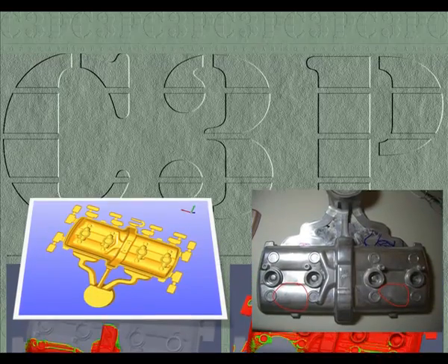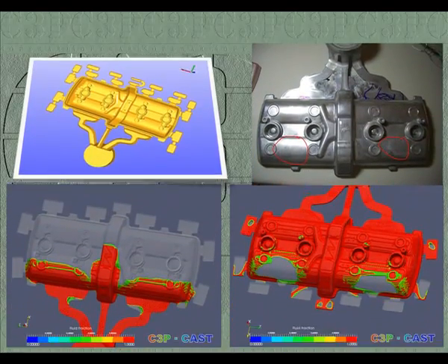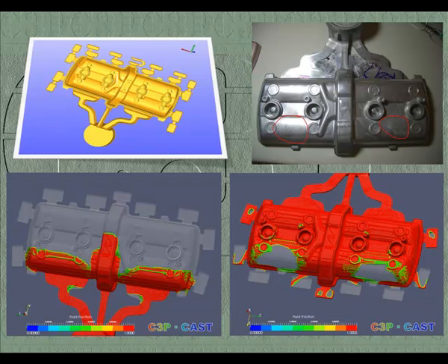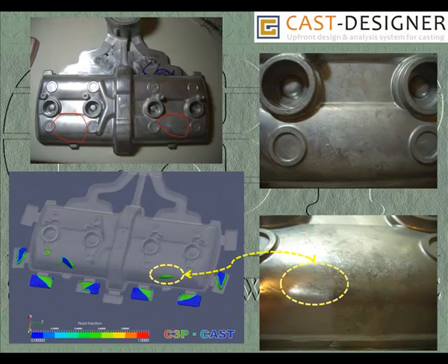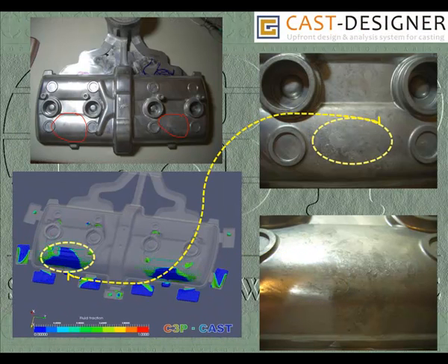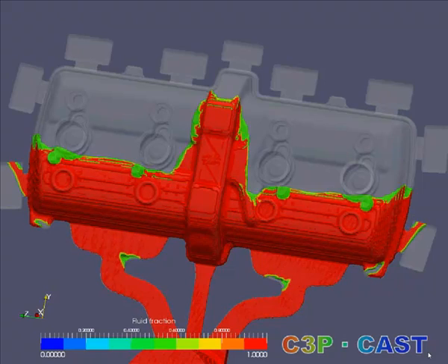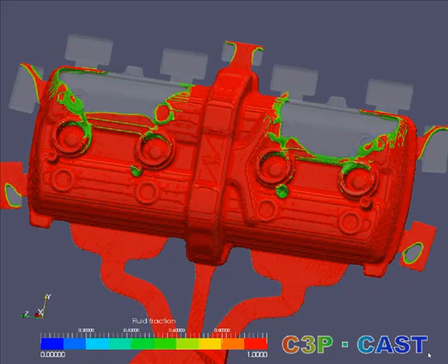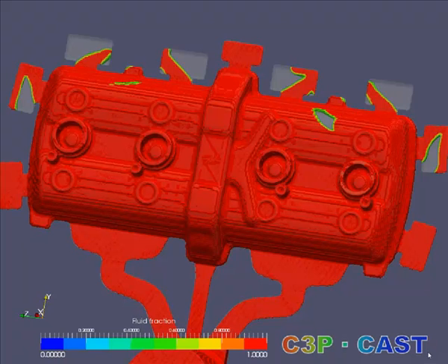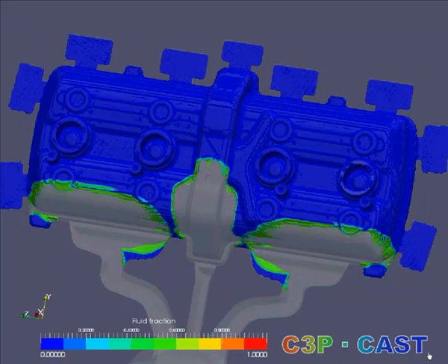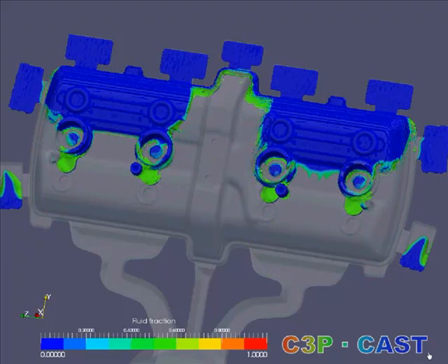CPI simulation can help predict such problems. It is clear the air entrapment was caused by the unbalanced metal flow. It mainly depends on the gating system. Also, the overflow system was not designed well. Simulation always provides rich information for engineers to check the real situation and find a good solution. The metal flow process, both hot metal and air, can be predicted very well.